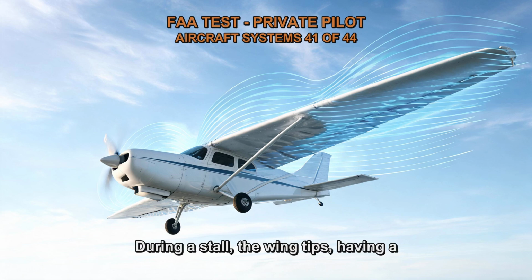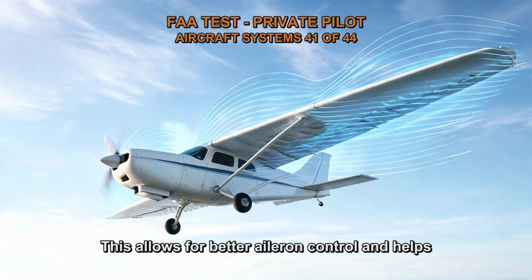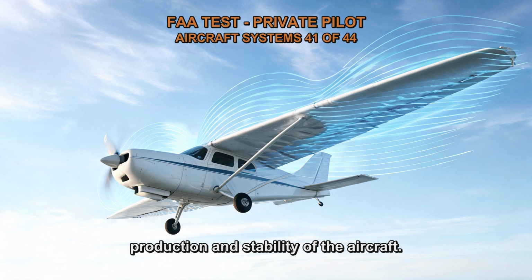the aircraft. During a stall, the wing tips, having a lower angle of attack, continue to produce lift while the main body of the wing may be stalled. This allows for better aileron control and helps to prevent tip stall, improving the overall lift production and stability of